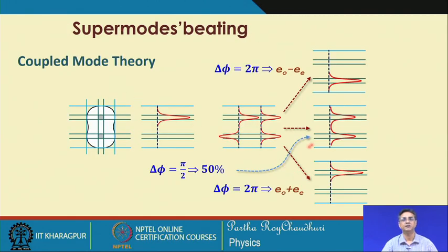To understand the same thing in the case of an optical fiber, you have a core here, you have another core here, and light is launched into this waveguide. At z equal to 0, we consider that this mode, which is in the first fiber, is a combination of the two lowest order super modes, that is, the normal modes, the modes of the total structure.